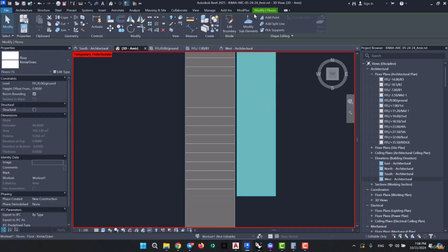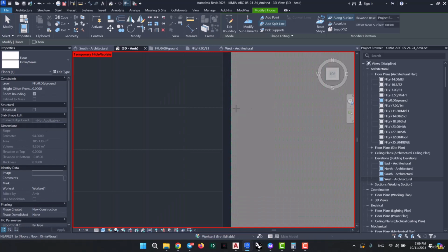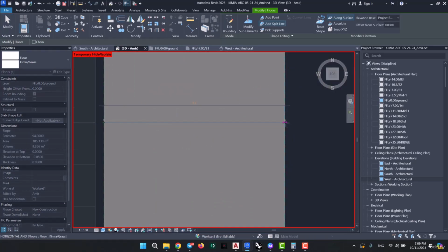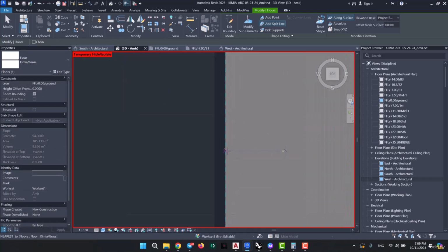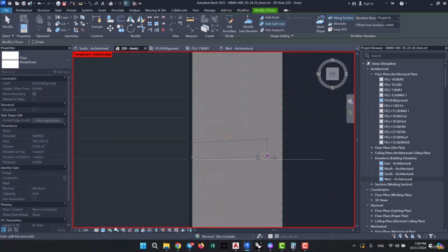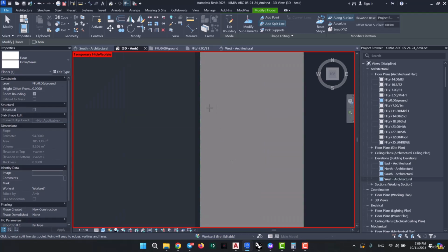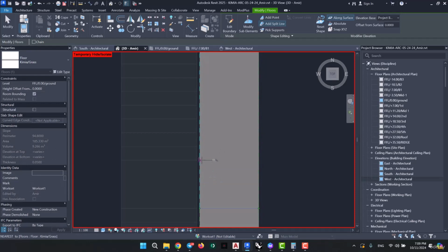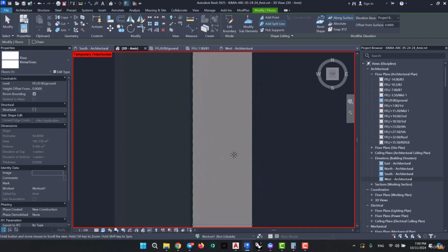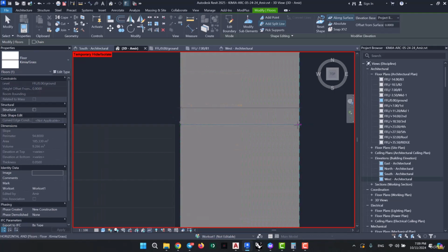Alright, now I'm going to select this, then click over here on Add Split Line. Then I'm going to draw a line right here along with this last step. And as for the second one, that'll be aligned with the first thread of the next flight. And also remember that drawing it close enough would suffice, but if you would like to draw it 100% precisely, you can go ahead and use a reference plane. But I'm just going to go by eye. And here goes the next split line. And as for the last split line, it goes here.